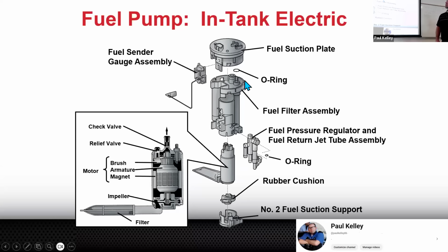And then this whole plastic housing. This actually has a fuel filter built into the top. Sometimes the fuel filter's here, and sometimes it's really only down here. Sometimes it has both, but a lot of times this is what we call the sock. It looks kind of like a sock, or the fuel pickup. And what's kind of interesting is when you slosh it around, a lot of times fuel will slosh into the sending unit, and then this sock sticks out the bottom. So it has a couple ways to pull the fuel.